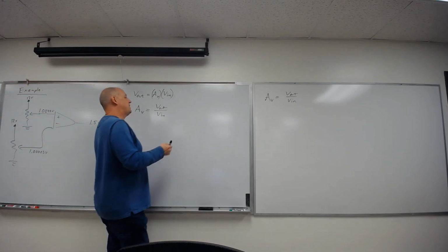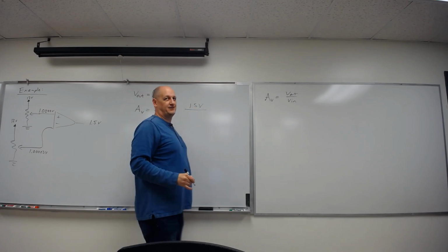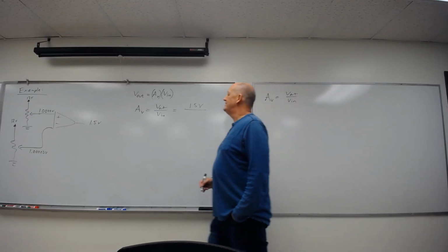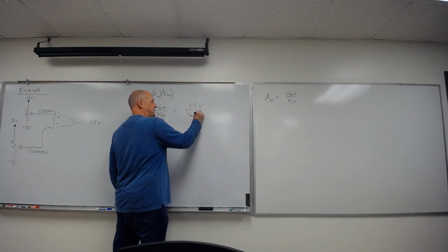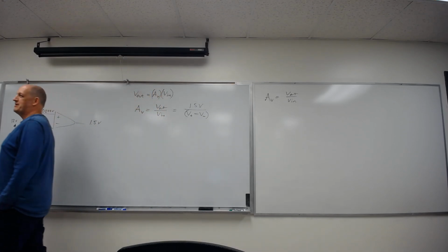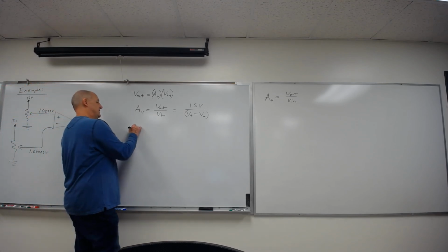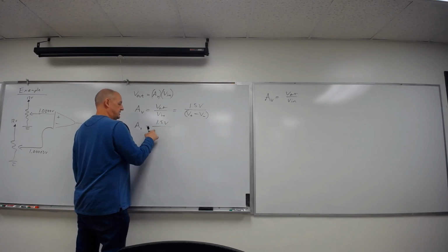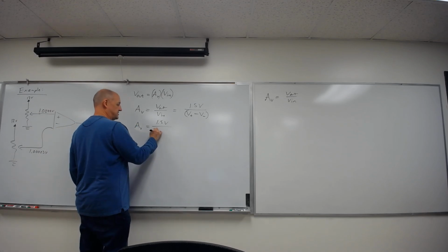All right, so what's the output voltage? What's the input voltage? There's 2 of them. Right, but what's the input voltage of an op amp? It's the non-inverting input minus the inverting input. Yeah, so remember I did some of these on Tuesday. I gave you the numbers. Well, I guess you give them here too. So 1.5 volts. I don't know if I have these lined up the way that one does, but that's okay. You can take the concept and solve your own.